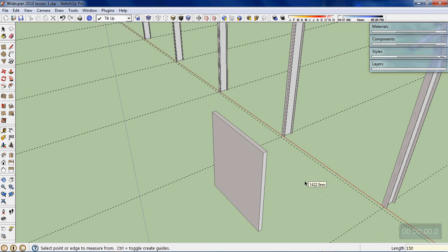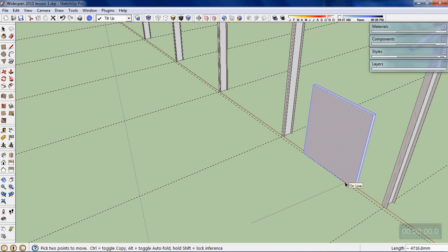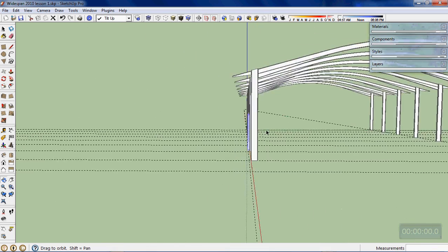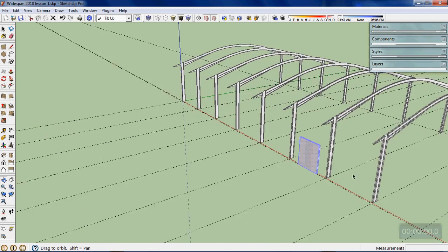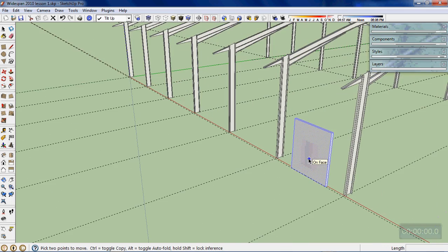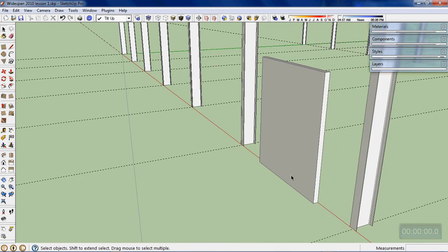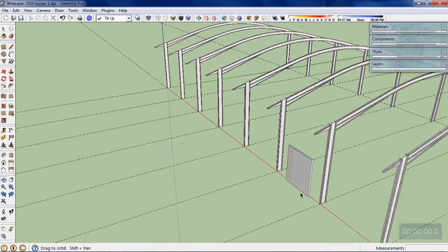I can then triple click my concrete tilt-up wall and move it from somewhere on this outside edge to somewhere on that set out line that we've just created. So in alignment it is now correct in the alignment of the plane of the wall, so I probably don't need this set out line again. I tend to get into the habit of, as soon as I've used these set out lines, start getting rid of them, because they will start to get in your road.